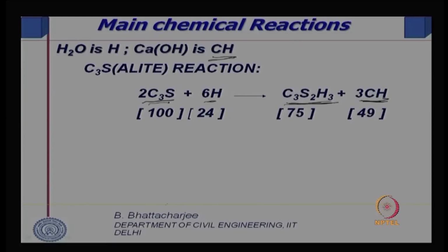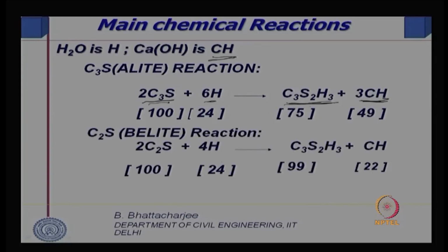Similarly, belite or C2S also reacts, forming calcium silicate hydrate and calcium hydroxide. C3S produces more calcium hydroxide than C2S.